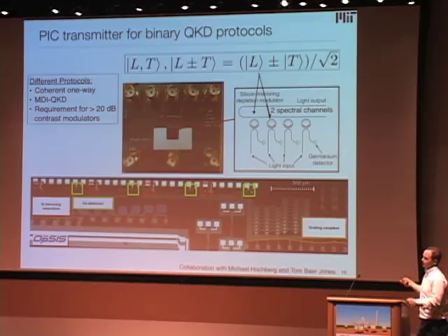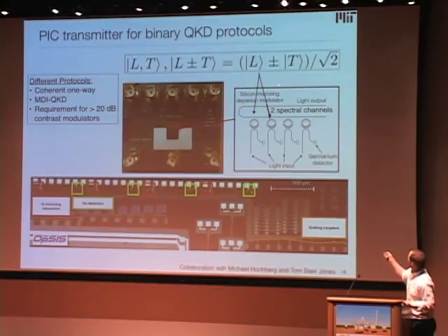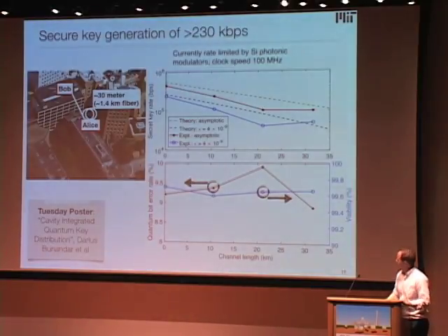And in this way, we can pulse carve either in the leading or trailing time bin, or in a superposition of the leading and trailing time bins, with a phase that's set by the path length, which is monolithically defined on the circuit, the path length between this and this ring. It's some tens of microns path length difference. We can tune that at a certain temperature to produce the pi and the minus pi offset in the phase.